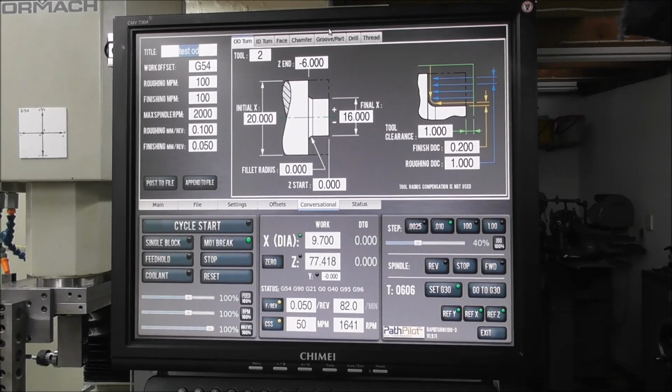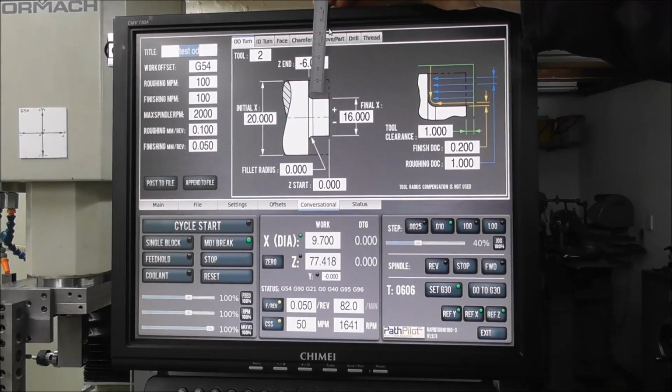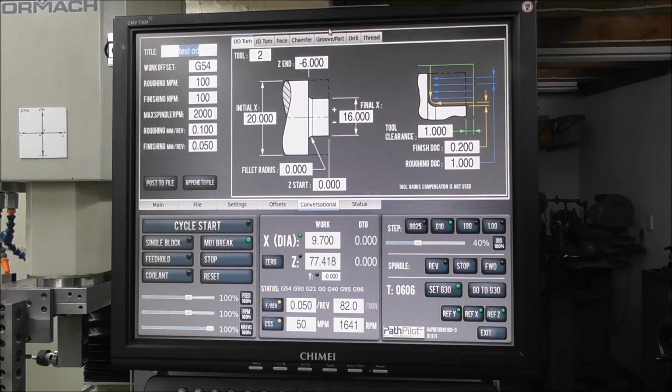Facing cut, finishing cut. But what's happening, I'll show you the program in a second, is that it's going 5.8, 5.8, 5.8, 6. So the whole tool is taking a full facing cut, and that's crazy dangerous. Am I missing something here? I'll show you the program.